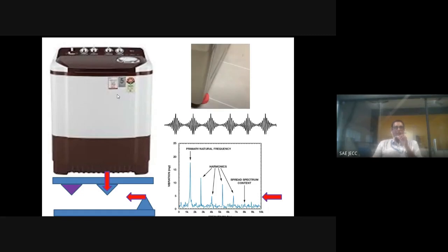So what is actually that process doing? You are making the mass distributed. Mass you are distributing means you are changing the system to have a different moment of inertia, because the K value, radius of gyration, is changing, correspondingly moment of inertia is changing, and in effect that will change the vibrating nature of the system.